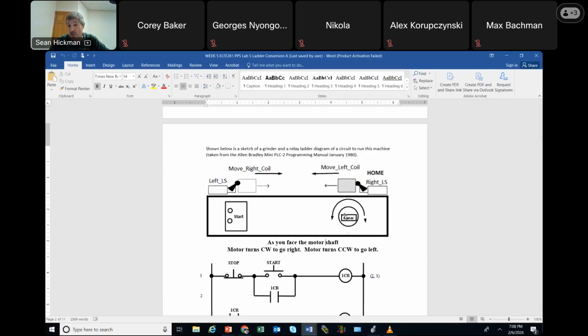And remember, if it's not working like you want it to, you could always switch one of the 3-phase leads coming in directly out of the disconnect, and then everything runs backward the other way, right? Seems like stamping in PLC1. Yeah, this is going to be a lot. Yeah, it has components of that. So figure out the motor direction to move right and to move left.